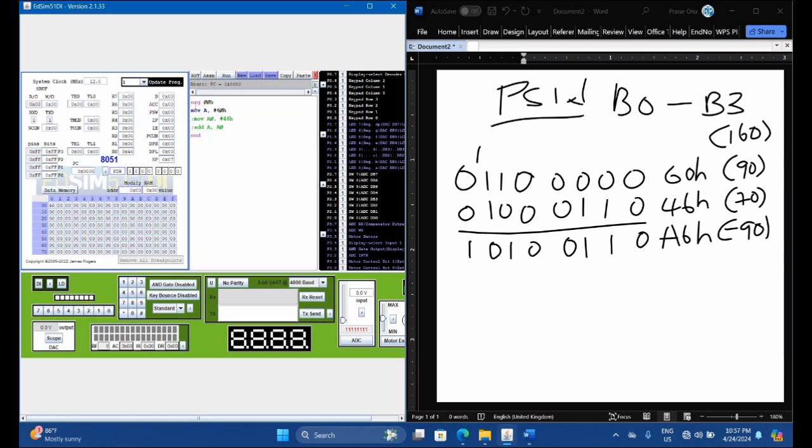Pause and reset. I will now comment this and open this, and I'll run and see. Nope, sorry, no. This should be in the accumulator A. Let's run. Yeah, so it's in the accumulator. We run this, we have 46. We have moved it to the accumulator. And 46 has 3 ones, so it means our parity would be 1.